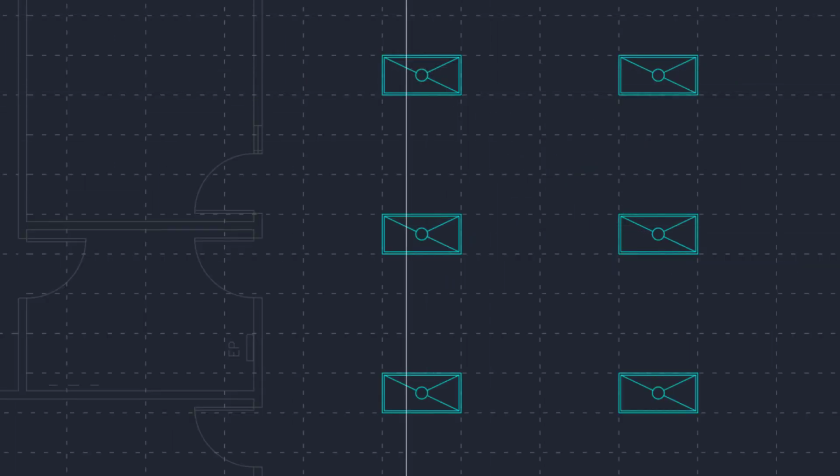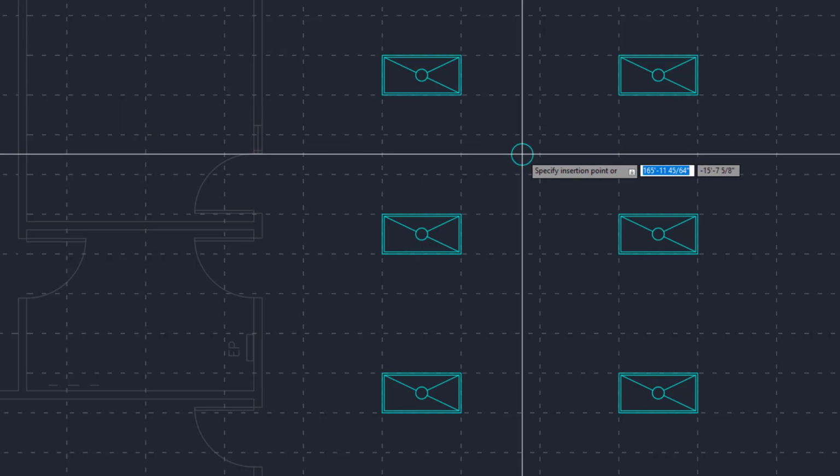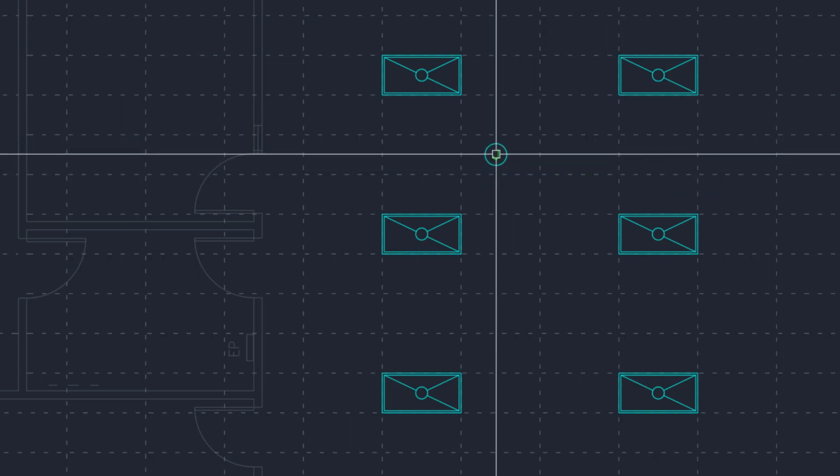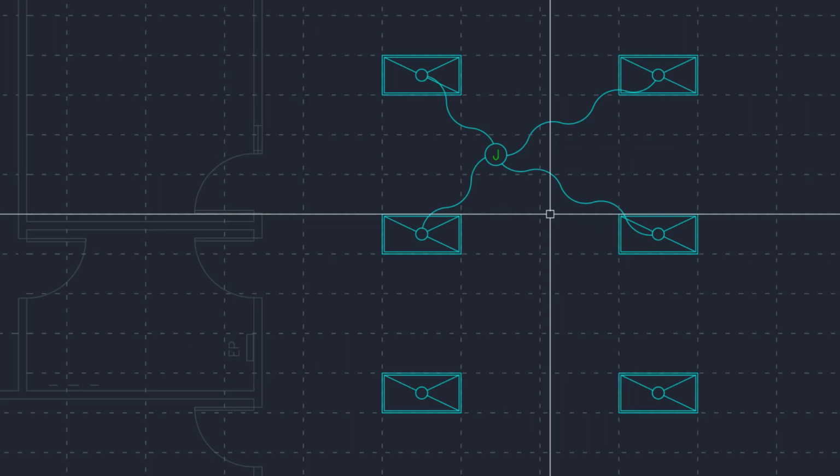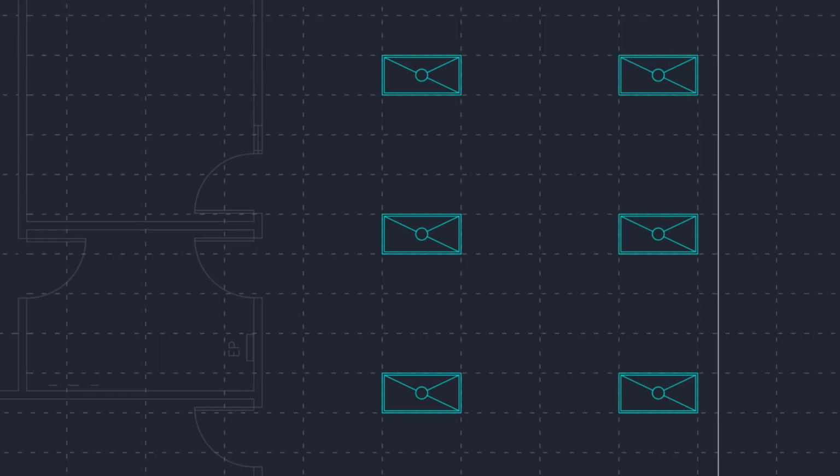I can go to the block library and pick a junction box and put it anywhere I want, and then go to auto join and do that, and it'll connect them. So that's one way. Let me do undo, undo, undo, and let me do the last way that I can think of. So I picked join fixture whips, and let's say I want a junction box in the center of this T-bar. I don't know why I would want to do that, but let's say I do.